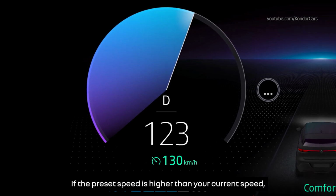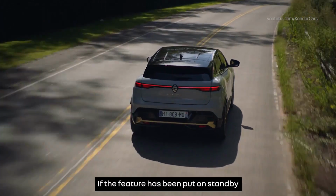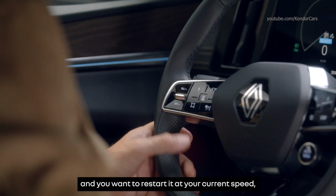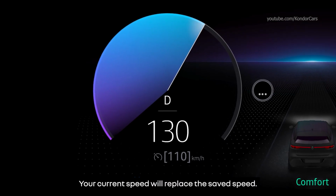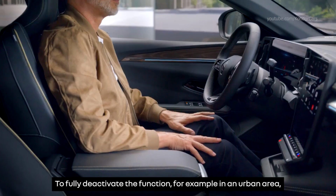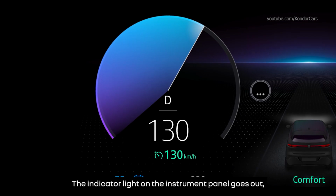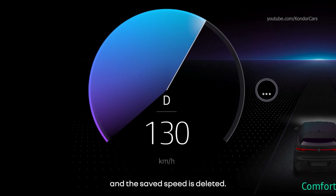If the preset speed is higher than your current speed, your vehicle will accelerate to reach the cruise speed. If the feature has been put on standby and you want to restart it at your current speed, push this switch down. Your current speed will replace the saved speed. To fully deactivate the function, for example in an urban area, press this switch. The indicator light on the instrument panel goes out and the saved speed is deleted.